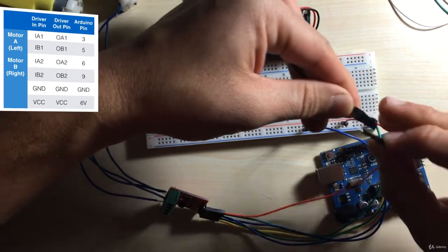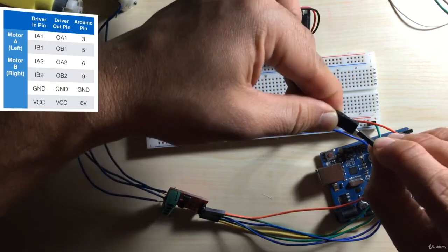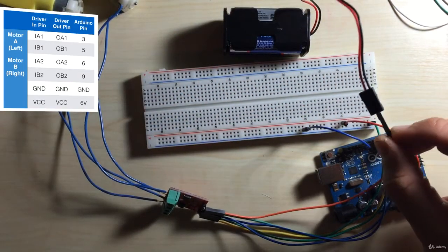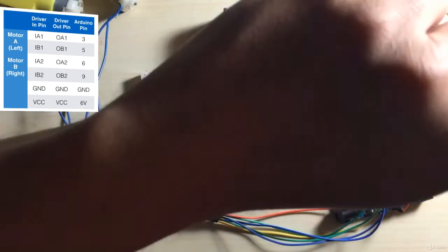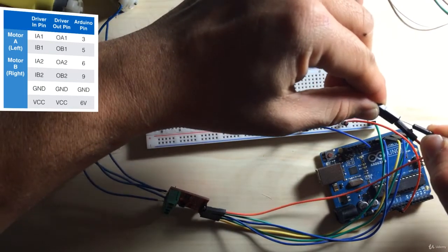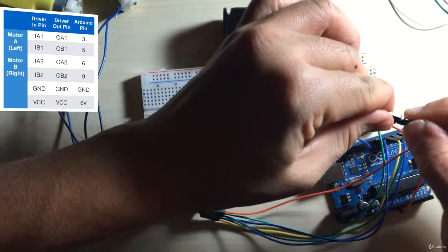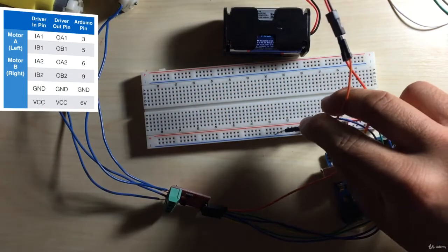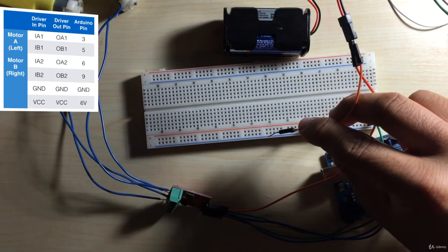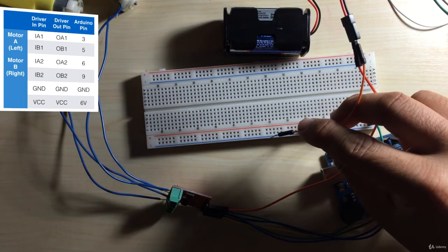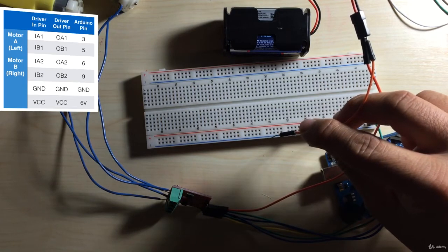So it's going to go into that red connection here where the red wire is, and the black is going to be grounded. So from the black here of our power source, we can go to ground on our circuit. Alright, so I'm not going to put this in here yet. When we actually upload the code, then I'll connect this to our motors. So we'll do that a little later on.